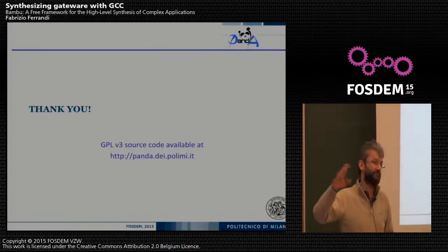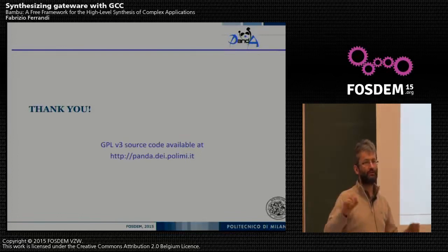Sometimes I start from a VHDL description of available floating point units, and I try to rewrite everything in C. Actually, most of the time you have to deal with bit sizes, but that can be controlled in C through masking and saying that a value is not greater than some bound, and so on. The compiler is pretty clever at this, since, for example, GCC 4.9 started to support value range, and so we just have to add bit value analysis, and so on.